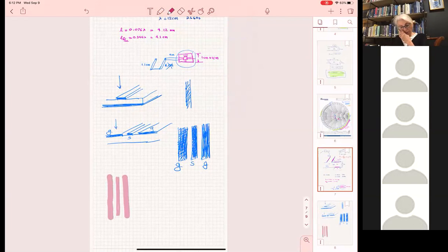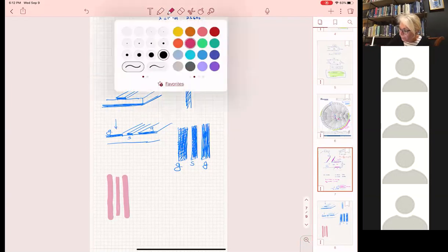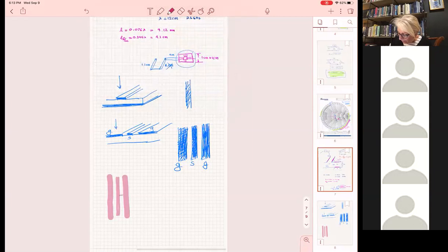This is coplanar waveguide, all right? And I would like to put in series a shorted stub. How is it going to look? My shorted stub in series is going to look like this. I have to do it symmetric on both sides. That's a shorted stub. Do you see how it is?